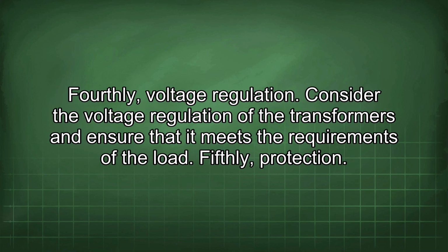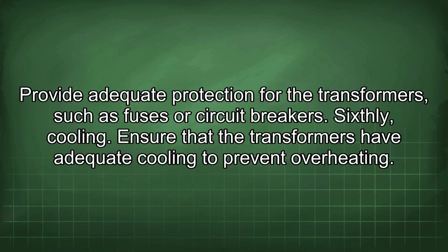Fourthly, voltage regulation. Consider the voltage regulation of the transformers and ensure that it meets the requirements of the load. Fifthly, protection. Provide adequate protection for the transformers, such as fuses or circuit breakers. Sixthly, cooling. Ensure that the transformers have adequate cooling to prevent overheating.